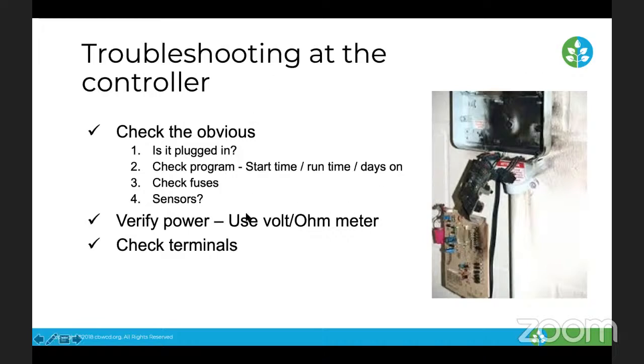Fuses, older controllers have fuses. If the fuse has popped, the irrigation won't run. You want to verify that you have power to it and check the terminals.